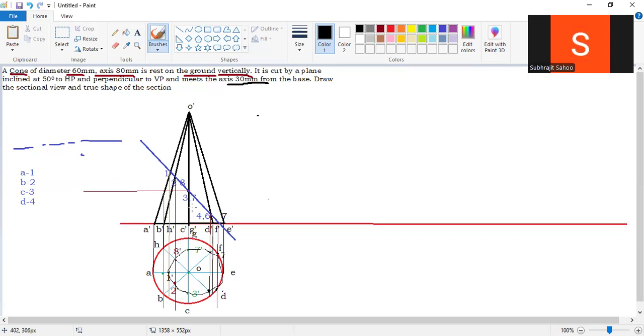Here, sir, after the circle you have done, this is called the sectional view. But here one more important work is pending. What is that? Hatching line. So you have to do the hatching line. I told you to set the 45-degree drafter. Like this line, for this circle, what we have just produced, there you have to draw the hatching line.